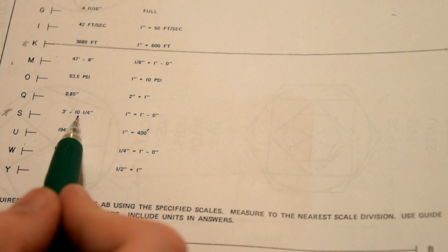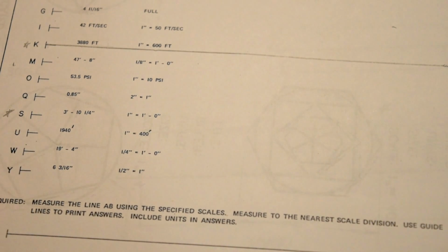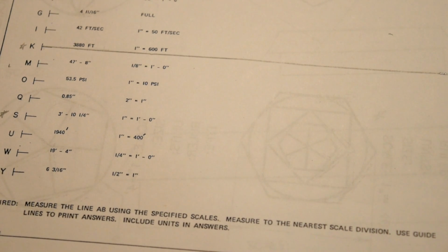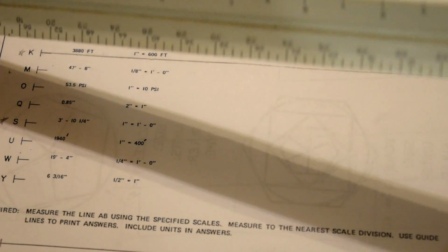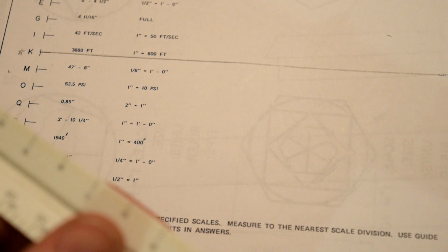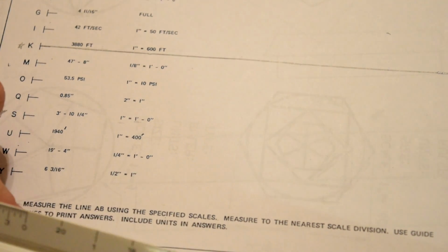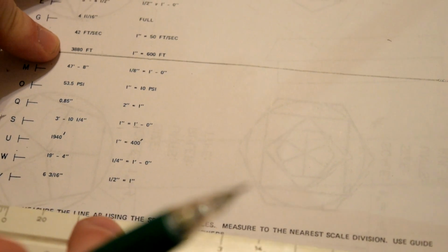Okay, so the next one I'm going to do is a line that's going to be 3 feet 10 1/4 inches, and the scale that I'm selecting is 1 inch equals a foot. Since that is a ratio of 1 to 12, that's not going to be very nice for my engineering scale. So I'm going to grab my architect scale instead, and I'm just going to use my 1 scale here. I'm choosing a 1 scale because both my paper and real scale sizes start with a 1, so I think that's going to work out nicely.